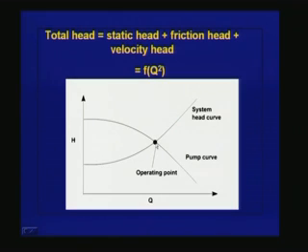Now this operating point should coincide with the best efficiency point or the rated point if you have selected the pump properly or if you have designed the pump properly to suit the given system.